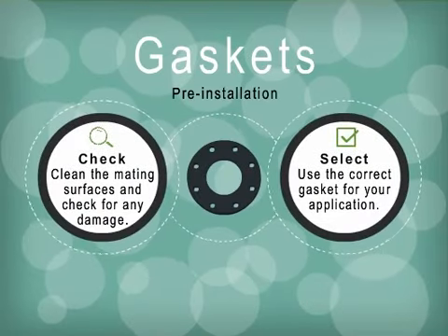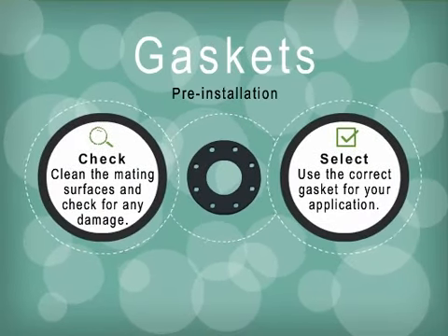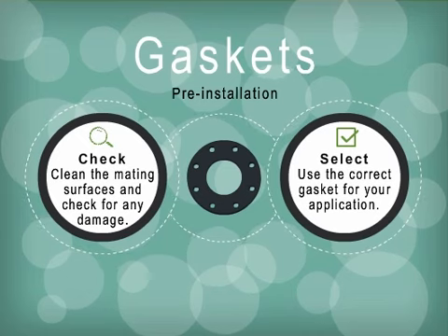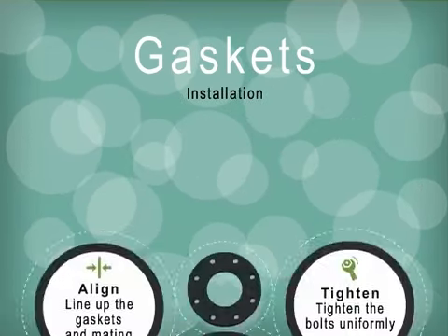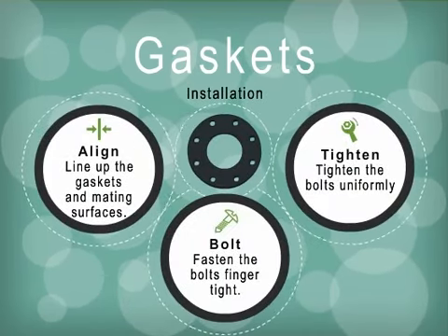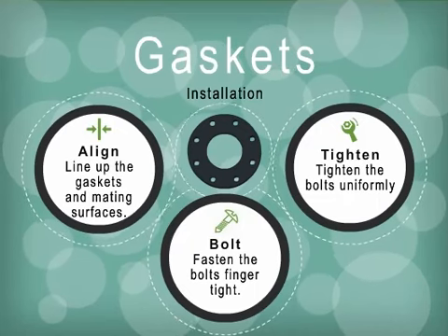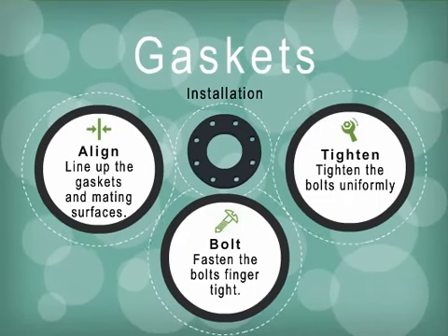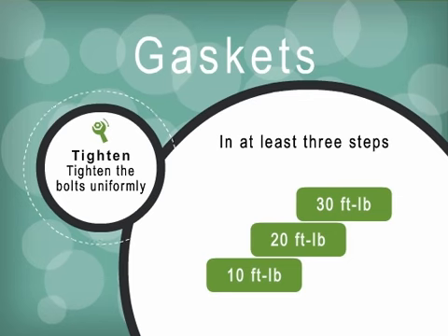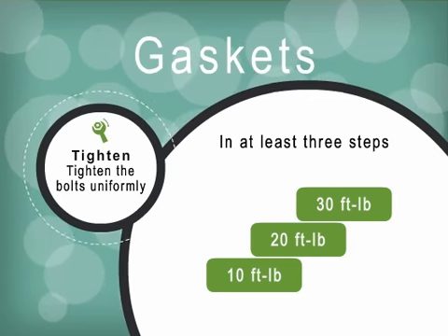Before installing a gasket between two mating surfaces, you need to follow the guidelines shown here. For a proper gasket installation, follow these steps. Make sure to follow the manufacturer's recommendations. For many applications, tighten the bolts in at least 3 steps.